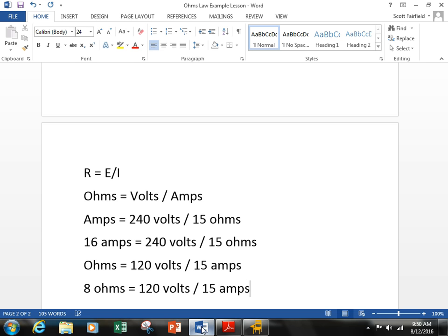So what's supposed to happen with your overcurrent protection is, if we have an excessive amount of resistance that causes the wires to overheat, or we're exceeding our ampacity, too many amps for the wire that's listed, then the breaker should trip off. The fuse blows or the circuit breaker trips, and we have to solve the problem before we reset it, because it'll trip again until we get the problem solved. So that's part of keeping the house from burning down because of an electrical problem.